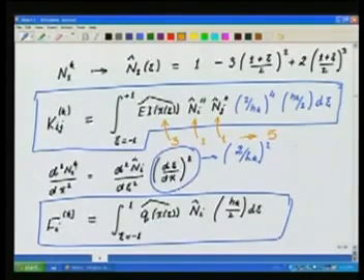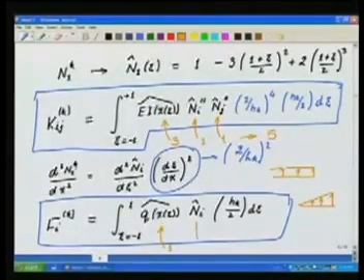Okay. Similarly, if I look at Fi, let us say that I am interested at most in a loading which is linear, that is I will have the constant loading and I have the stepped loading, the triangular profile. Okay. So, the loading is linear. So, if the loading is linear, the q is linear, Ni is cubic. So, here the integrand is of order 4. Okay.